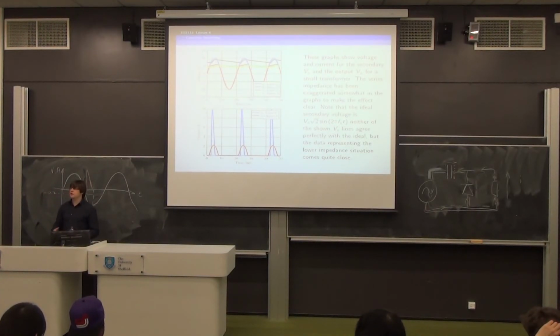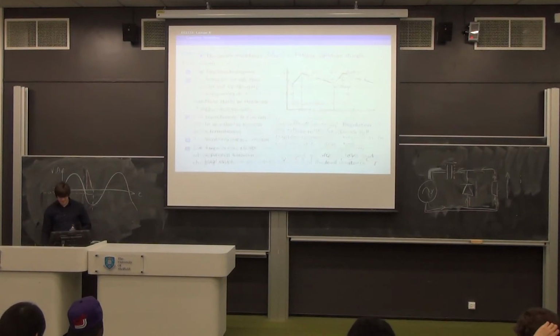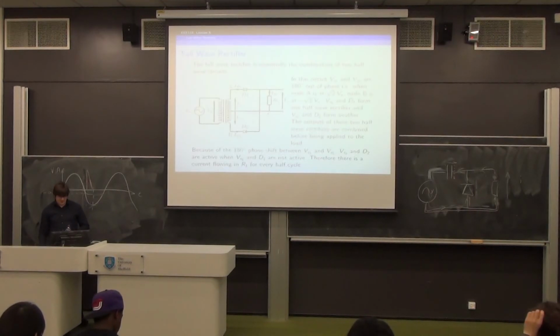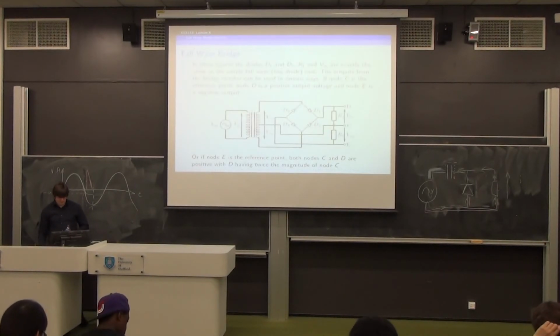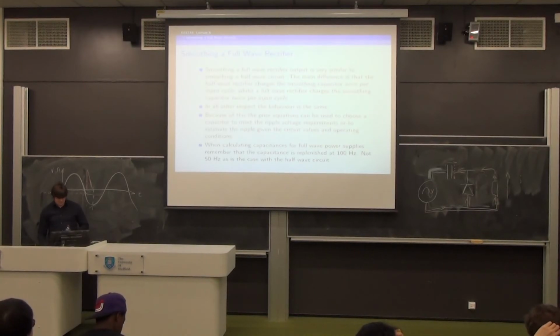But when you come to do the calculations, the only thing you have to remember that's different is capacitors are refreshed at twice the input frequency in full wave, and at the input frequency in half wave. In all other respects, behaviour is the same.